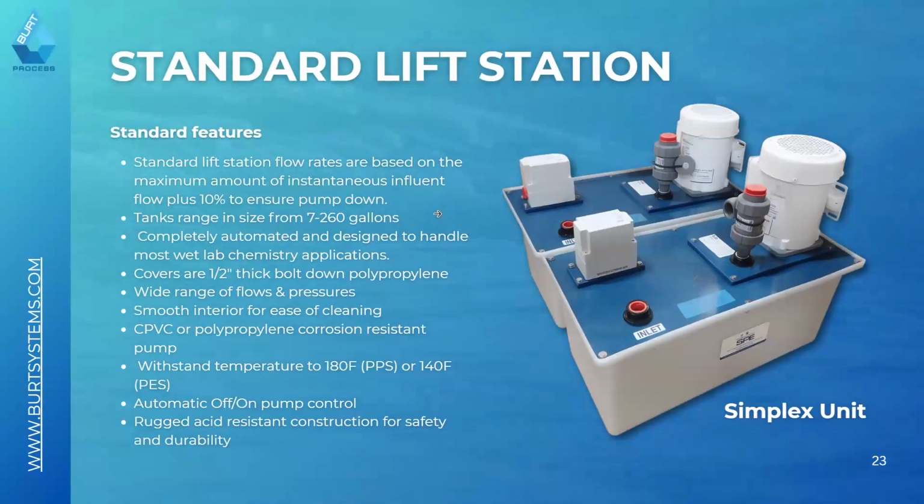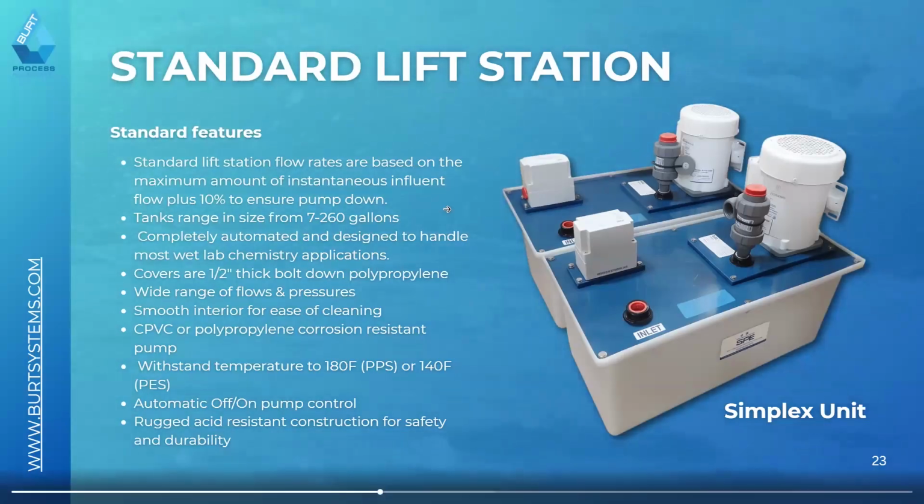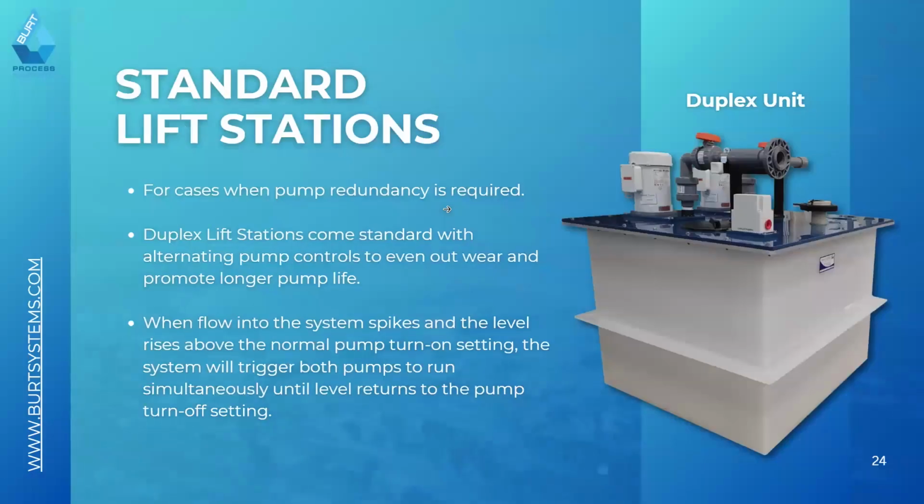So very small lift stations, things that are like under the sink, are sort of specialty. They have more of a simplex design. Simplex is obviously not common when you're talking about different types of waste transfer systems. It really is only utilized when you don't need redundancy of a single process. See, downtime is not very important as part of these types of systems.